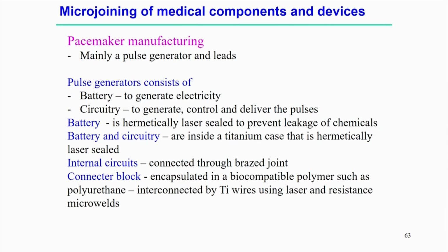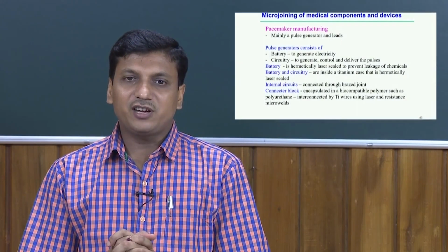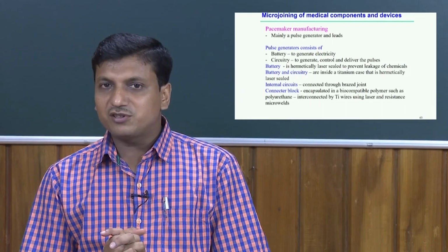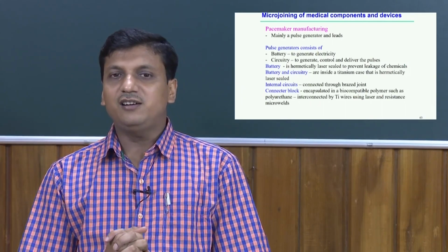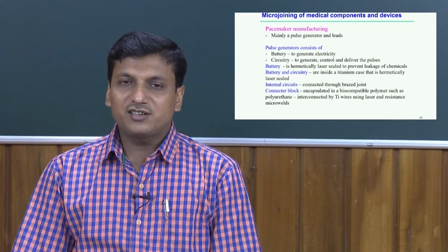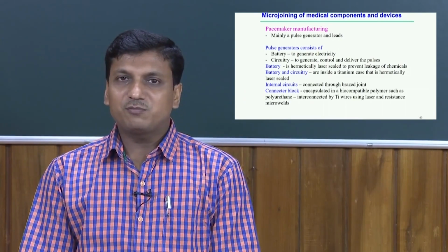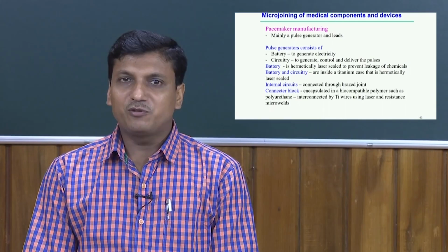Of course, in this pacemaker the internal circuits are generally connected through the brazing process, but the connector block is sometimes encapsulated in a biocompatible polymer such as polyurethane. It is interconnected by titanium wire, and the typical welding process here uses either laser or resistance micro welding processes.